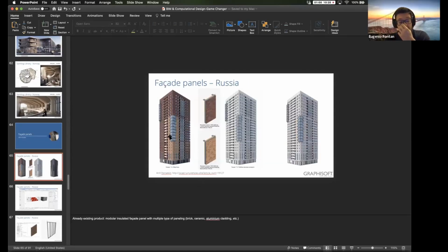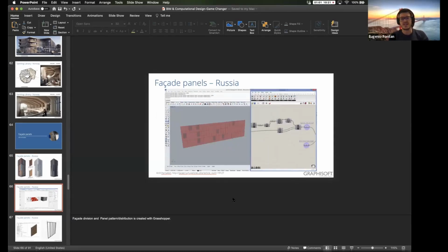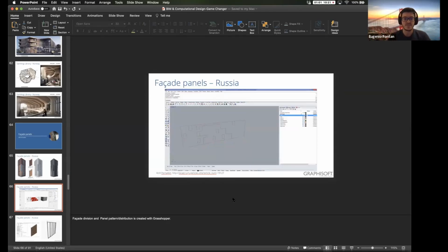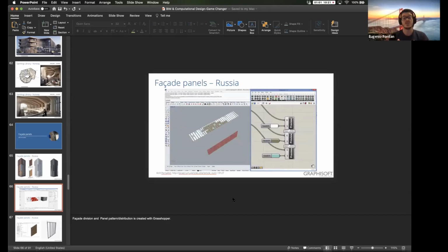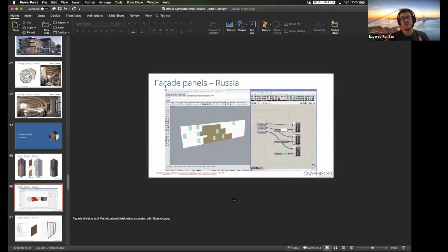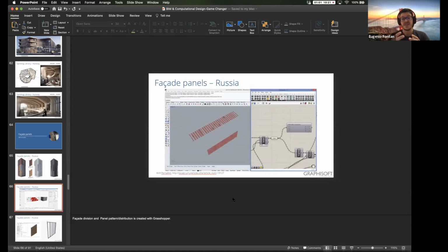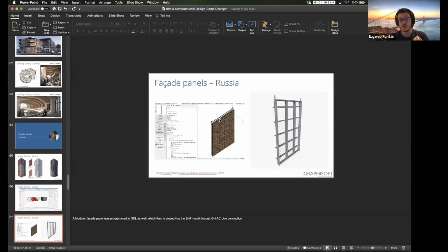Yeah, so the idea is that first there is a step, in this case in Grasshopper, in which the architects analyze the facade, and in Grasshopper they create these panels. Okay, but as we were seeing in Grasshopper, these panels are a set of surfaces, lines, and volumes. And then using the connection between Rhino Grasshopper and Archicad, those geometries become these elements that are part of the construction model. So it's like completing the workflow.